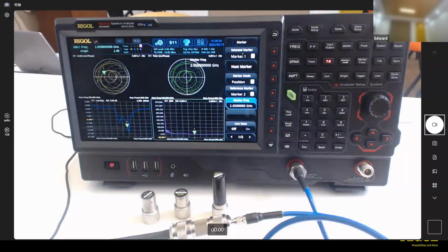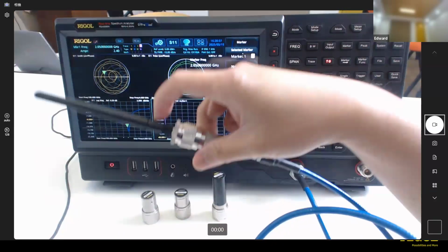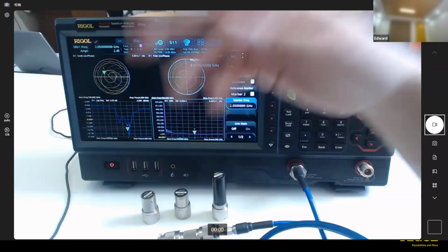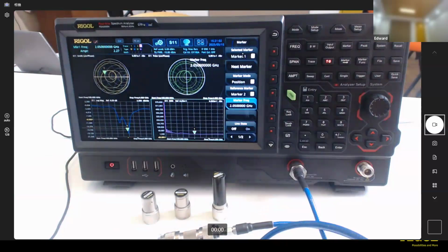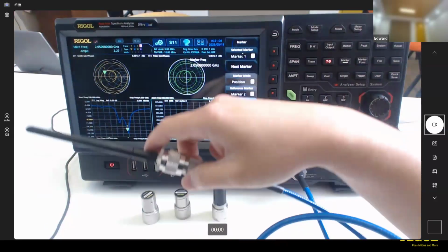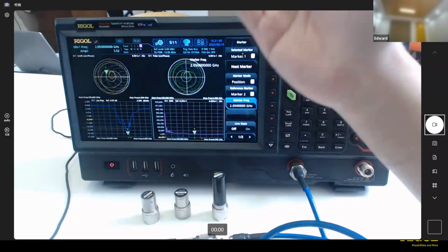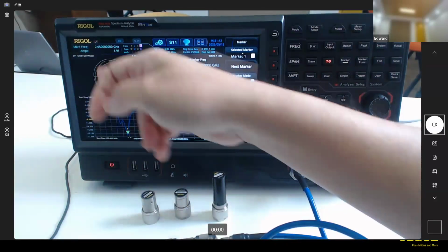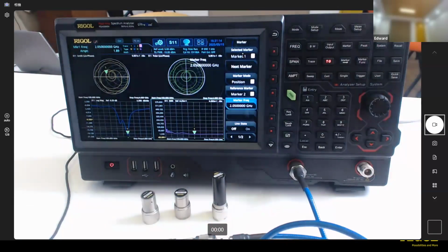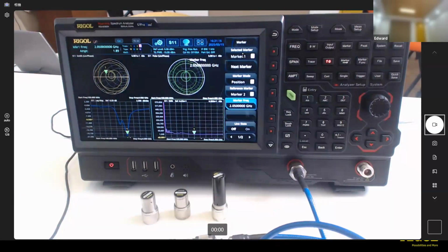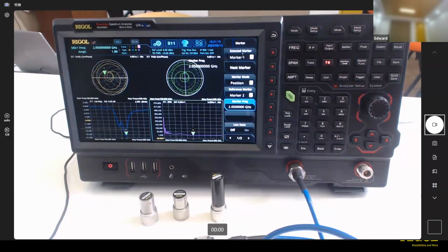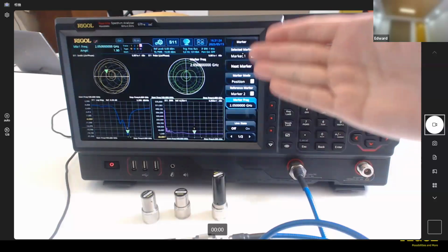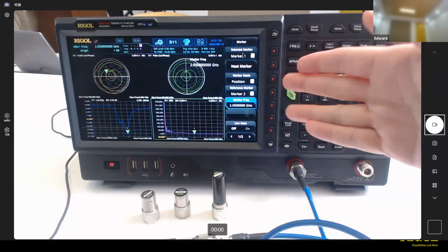It is a very simple and cheaper one, so I think it has some deviations and worse performance, but no worry about that. On average, the resonant point is very accurate, at 2.36 gigahertz. So that is a very simple live demonstration about the port extension, right?